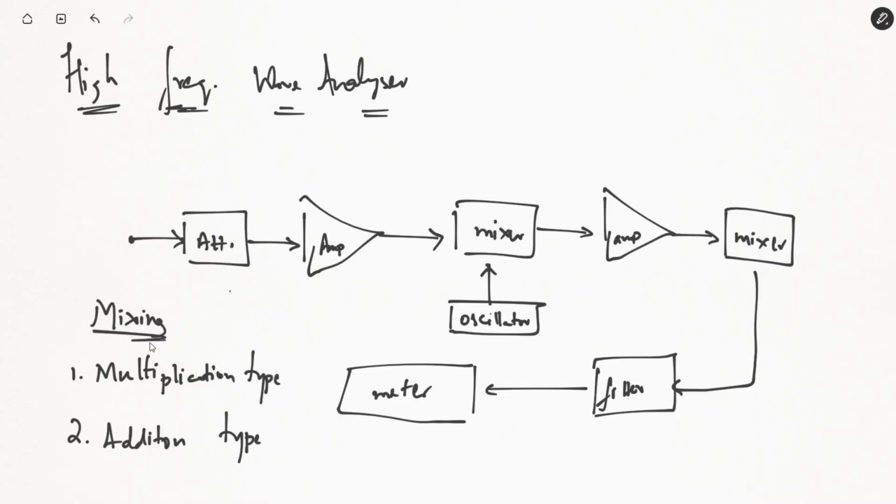Right. So you are mixing the AM frequency with the RF frequency to produce another signal of frequency that will be at intermediate frequency, and our filter is already tuned to this intermediate frequency level so as to analyze that particular frequency component for measurement of its amplitude voltage.